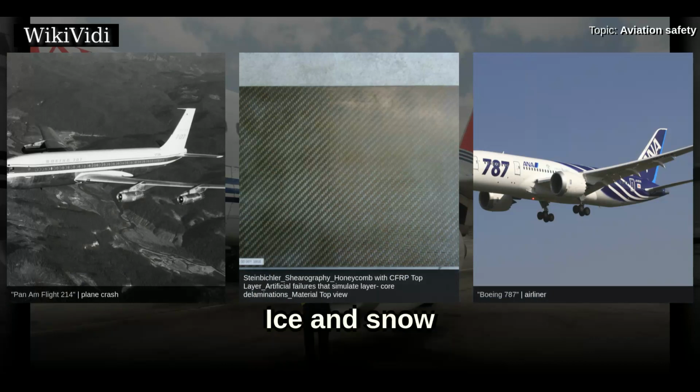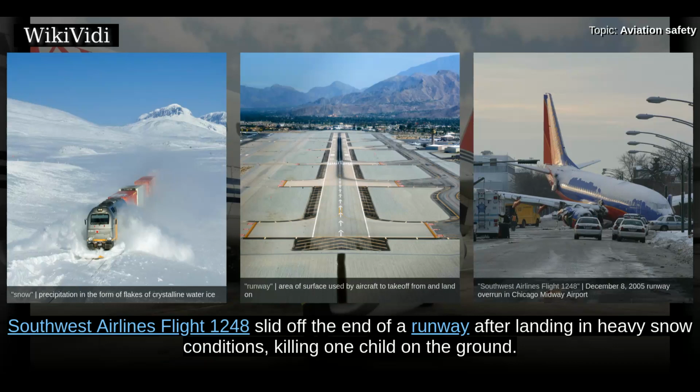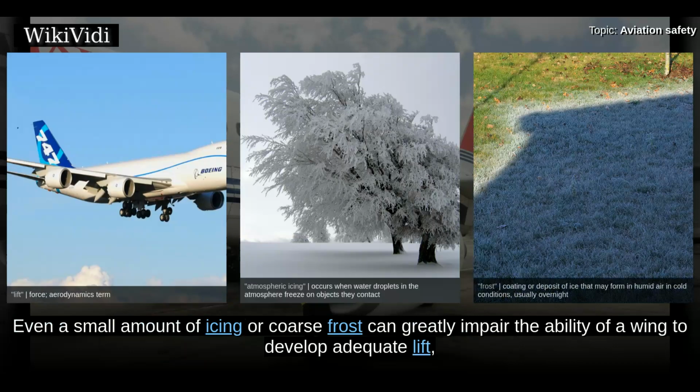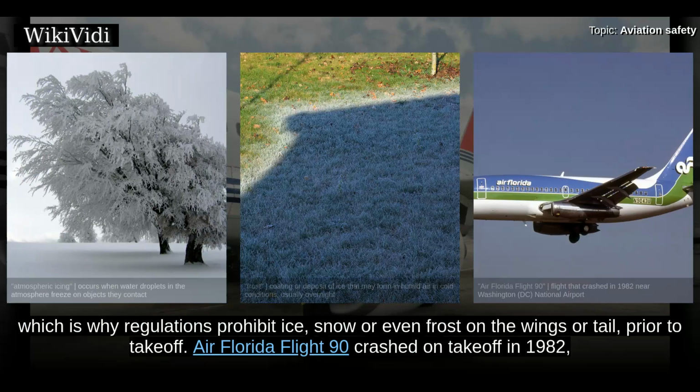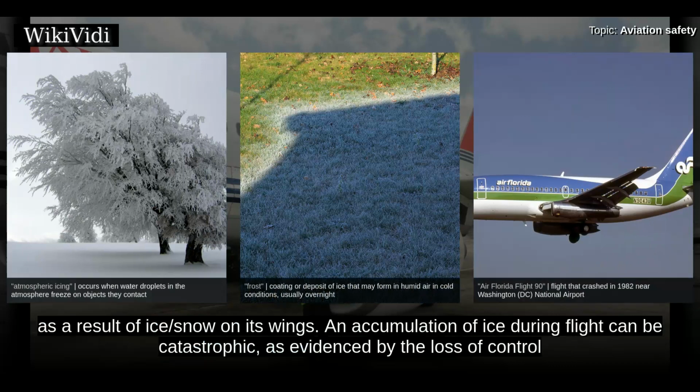Ice and snow. Ice and snow can be major factors in airline accidents. In 2005, Southwest Airlines Flight 1248 slid off the end of a runway after landing in heavy snow conditions, killing one child on the ground. Even a small amount of icing or coarse frost can greatly impair the ability of a wing to develop adequate lift, which is why regulations prohibit ice, snow or even frost on the wings or tail prior to takeoff. Air Florida Flight 90 crashed on takeoff in 1982 as a result of ice and snow on its wings.